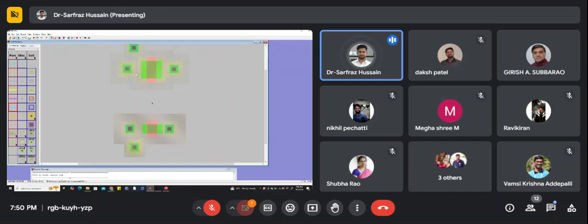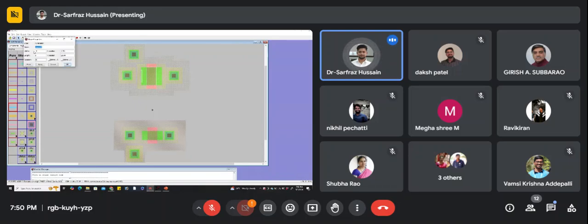Okay. Now we need to connect these both. One will act as a source, another will act as a drain. Because these two need to be connected together, so that we can connect this with this wire. In order to connect these two, we need a connection between the PMOS and this particular contact. Now, you can check here the size of this. We have taken the width as 10 and length as 5.